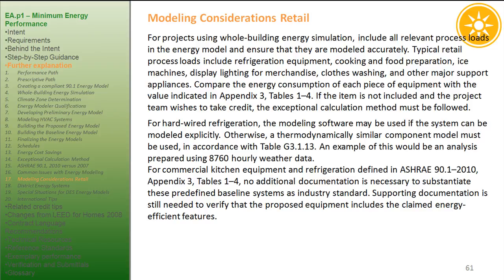Compare the energy consumption of each piece of equipment with the value indicated in Appendix 3, Tables 1 to 4. If the item is not included and the project team wishes to take credit, the exceptional calculation method must be followed.